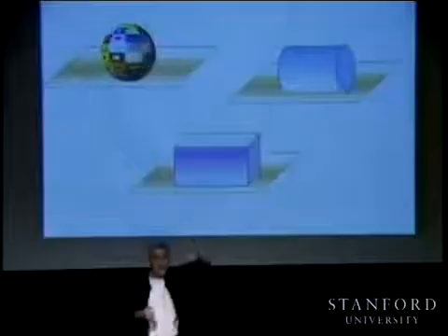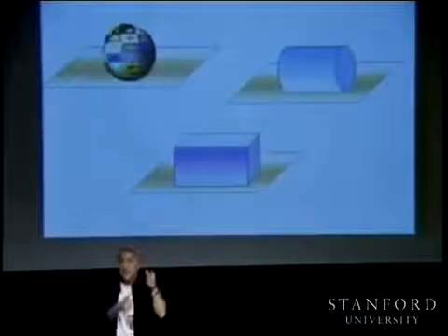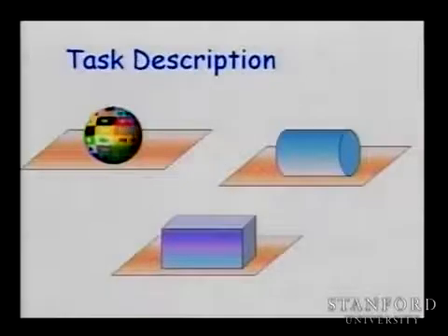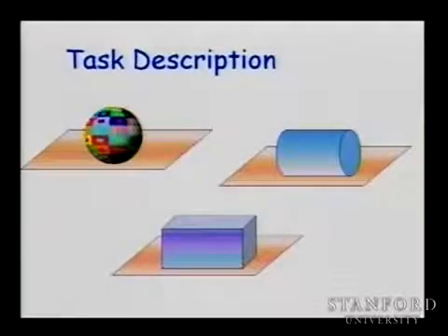But at the same time, did we really lose those degrees of freedom? Because if I'm pushing here or controlling this moment, I still can do it. I can push with 10 Newton, 20 Newton. So the degree of freedom just went to the space of force control. So in those contacts, if you are talking about controlling that variable, the force, then you didn't lose the degree of freedom. It went just into the constrained space, and you can control now that force. And we can now describe the directions and the relationship between the two and separate the spaces.